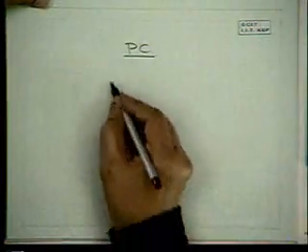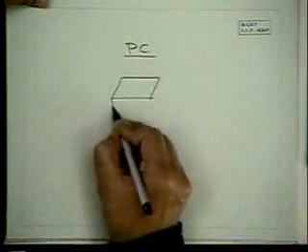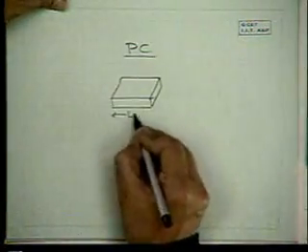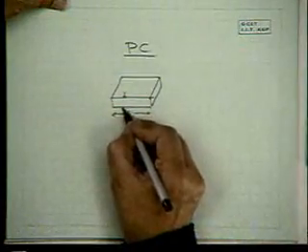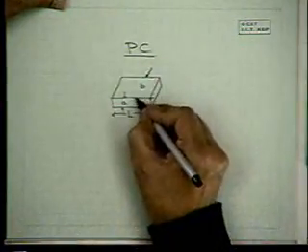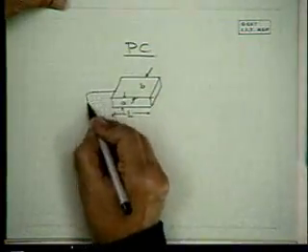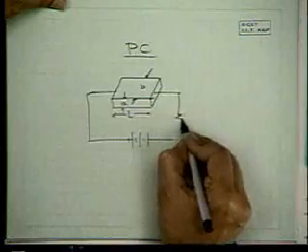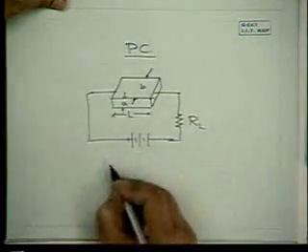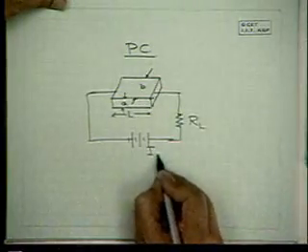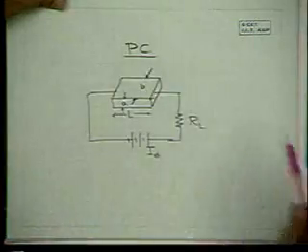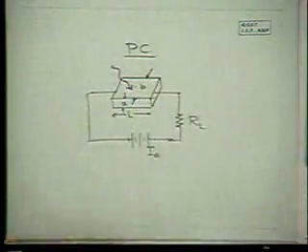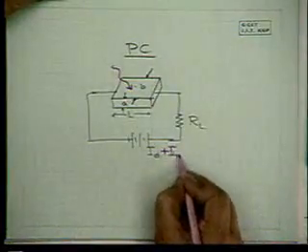Okay, so broadly, a photoconducting detector can be considered to be a slab of material with, say, length L, thickness A, and this dimension, say, B. There's a certain dark current flowing in the absence of light, depending upon the resistivity of the material, and when light is incident, we have an additional current I photo.